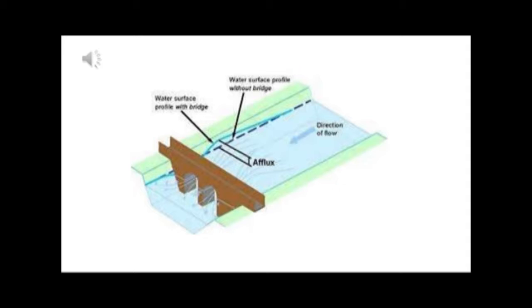Here in slide 7, we see a bridge passing through a river body and covering the obstruction, and we see a little rise in water level. The rise in water level is due to the obstruction in the waterway, which could be a channel, a flood channel, an irrigation channel, or a simple river or drainage basin.